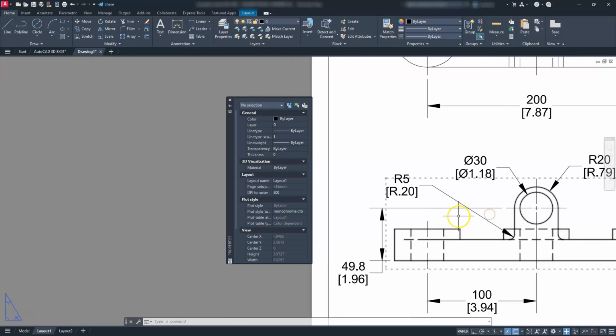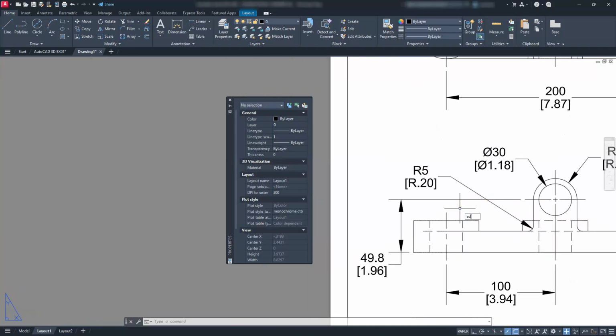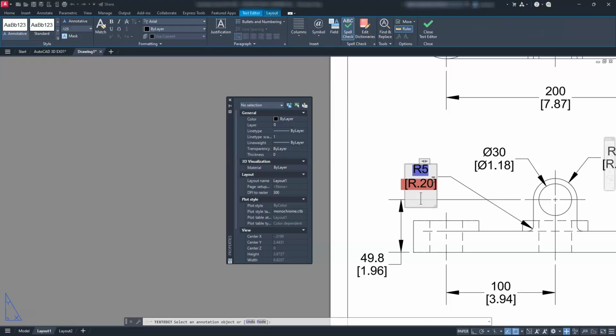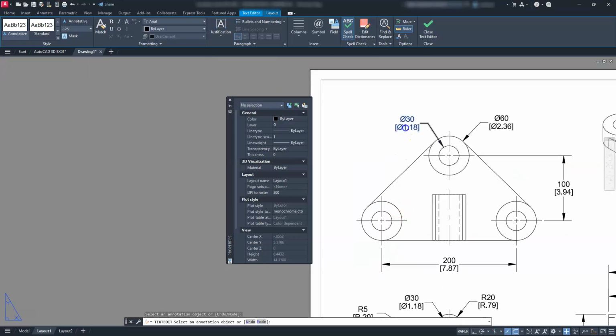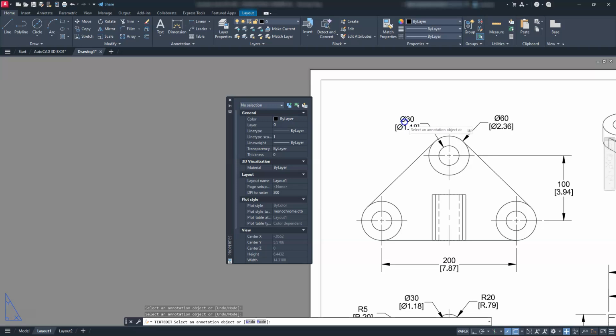Okay. Last thing we need to do is add some text to a couple of these dimensions, and we should be done. So I'm just going to select here. And what I usually like to do is hit the N button on my keyboard a couple of times. Then hit enter. Now I can type in 2 places. Some people will put typical or things of that nature. I tend to like to count it. It makes it a lot more accurate.